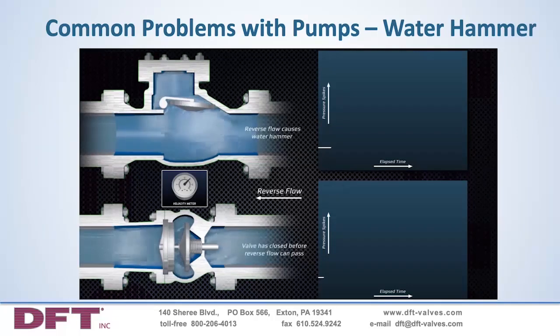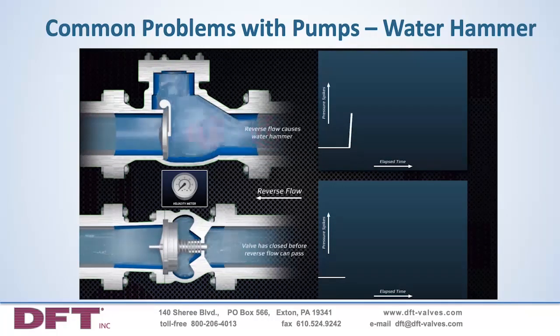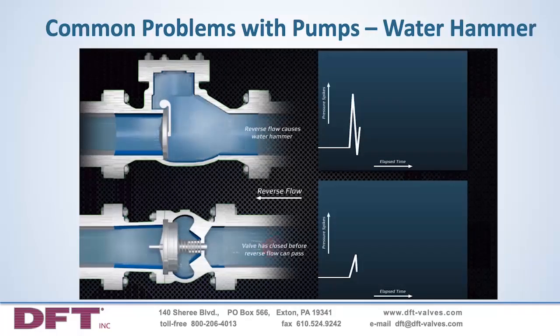Water hammer is a common issue in households, but it's also very common in industrial plants, and can manifest itself as a thumping or banging sound that in extreme cases can result in extensive and costly damage to expansion joints, pressure sensors, flow meters, pipe walls, and other valves.